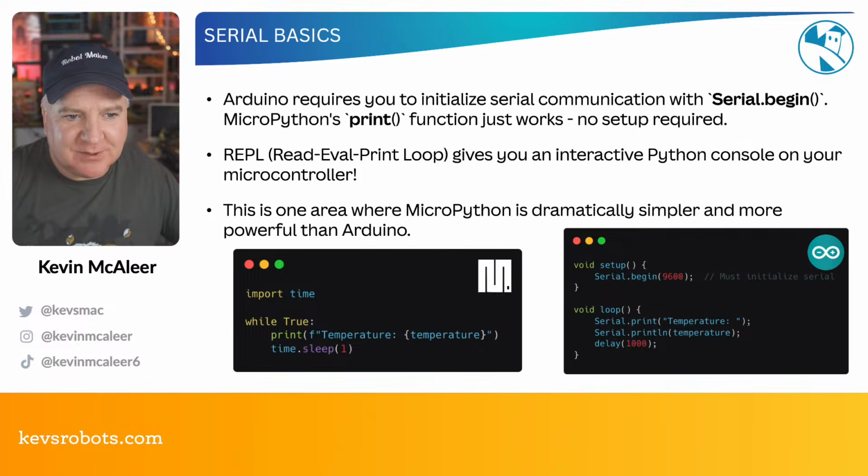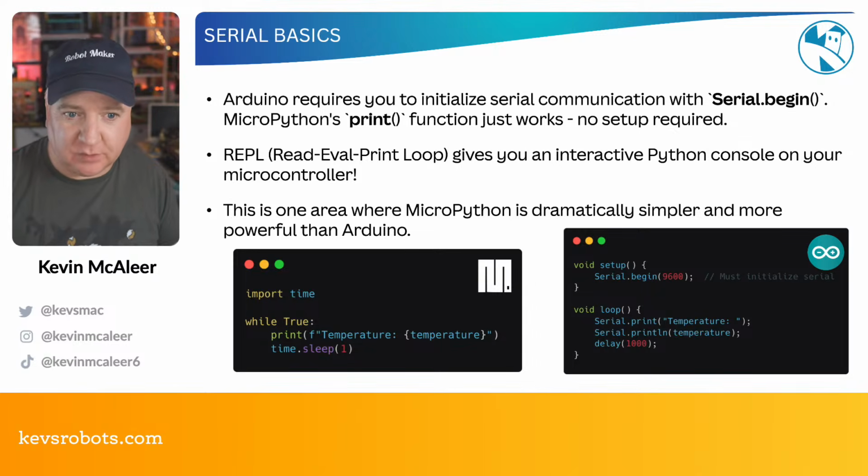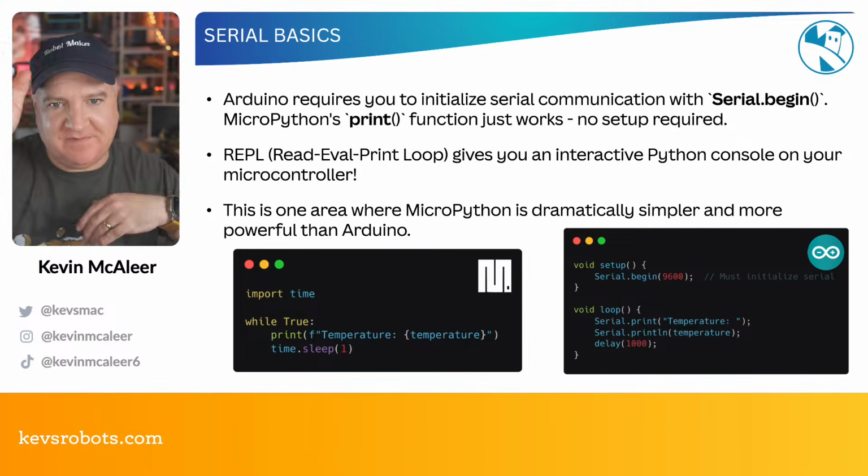Okay, serial basics. Arduino requires you to initialize the serial communication with Serial.begin. MicroPython's built-in print function just works. There's no setup required. So we always have this read, evaluate, print loop, the REPL, and that gives you an interactive Python console. You can actually start typing code the second the board boots up. So you can import time, while True, print temperature, and if you've got some kind of temperature value, it'll print that out to the terminal, and then we've got a time.sleep, so it doesn't just scroll off infinitely.